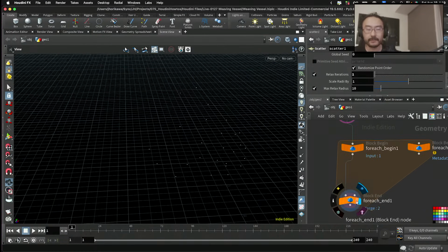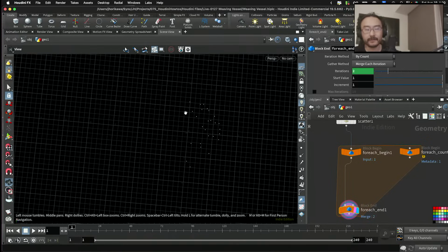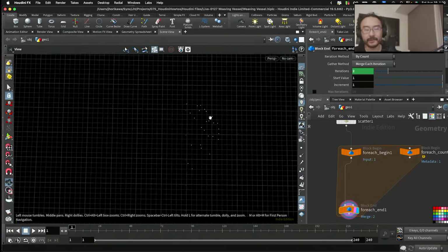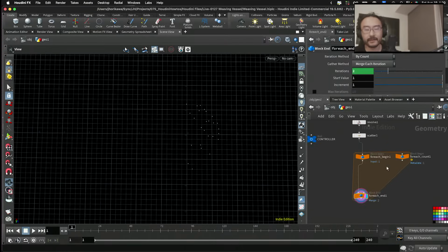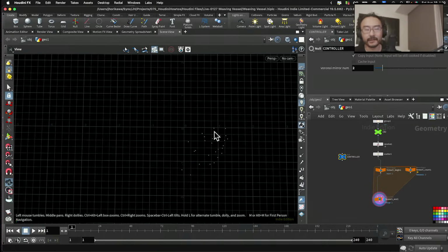go inside the loop, and what I want to do is to mirror these points on the other side. Because if I change this value, the angle will change, and if I make this to 2, you're going to have 4 surfaces. So these points should be mirrored to this side. These also get mirrored on this side as well. And the mirrored points somewhere on here should be again mirrored on here.